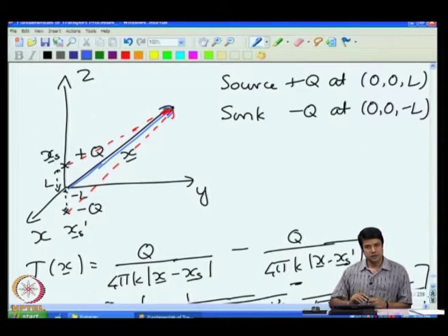And finally, I had made a connection between the spherical harmonic expansions and the point source formulation. The decaying harmonic solution for n equal to 0, the spherically symmetric decaying harmonic solution, is identical to the temperature field due to a point source.